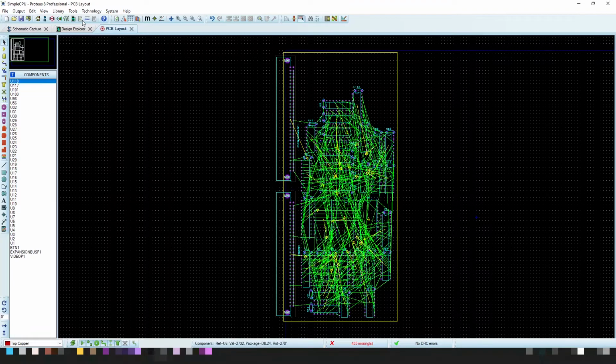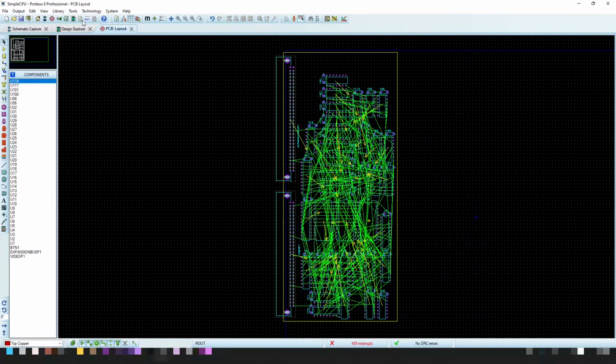You can do manual routing as well, but I have pretty much always consistently used the auto router because I don't want to spend a huge amount of time doing manual routing for everything. Some people really like doing manual routing. I don't like it at all. So I cheat. It's not really cheating to use the tool for what it's meant to, I don't think. It's like saying that using an optimizing assembler is cheating, or an optimizing compiler is cheating. It's not. It's using the best tools for the job, rather than trying to maintain a whole bunch of stuff with human effort. It's just not efficient, and it's not cost effective, in my view.